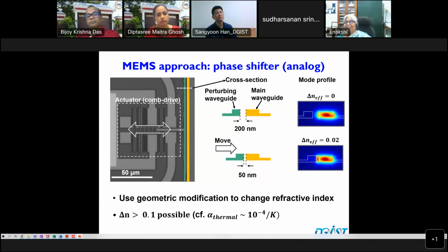Okay. And then finally, you have been using electrostatic actuation, which is easier to design, but you do use some piezoelectric material. What are your comments on actuation using piezoelectric instead of electrostatic? Okay. So for piezo, I think it's a good option. It has a stronger force and maybe somewhat faster, but it requires exotic material, and exotic material means a more complicated process. And the benefit is not huge compared to just silicon electrostatic. Okay. Right.